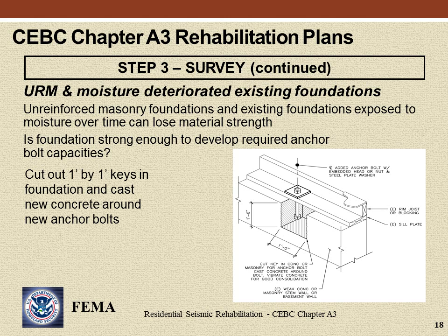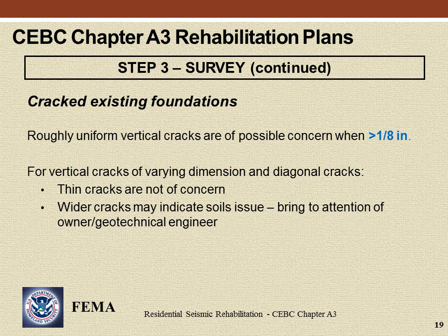This detail has had limited usage in Southern California. Judgment is required in deciding if this detail is adequate or if the foundation is so weak or deteriorated that foundation replacement is needed. Note that expansion bolts are not recommended for installation in weak foundations.